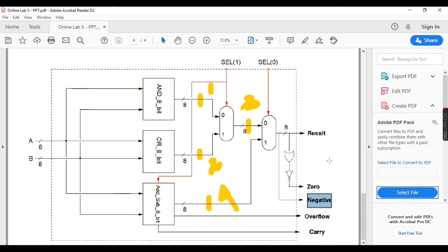In that case, each and every submodule we have designed on our own. So you could have designed this particular ALU using the behavioral way also. In that case, you can use a case statement to represent the functionality of the ALU. It will be very simple. If you search in Google, you will find the case statement syntax for VHDL, and probably also the corresponding code of an 8-bit ALU.